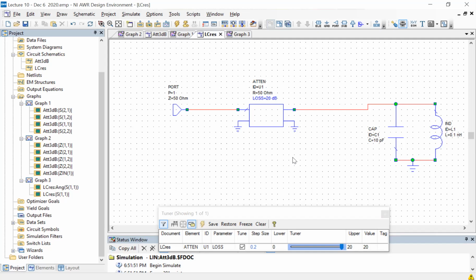So in this case, we are measuring the reflection using a single port. Yeah. But in experiment, we use 2 ports to measure the reflection, let's say. That's right. So how in this case is it measuring only from port 1? Even in experiments, when you do it at room temperature, you can measure a single port reflection coefficient. There's no problem with that.